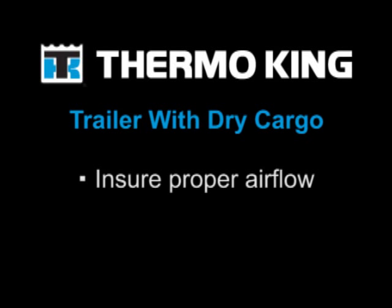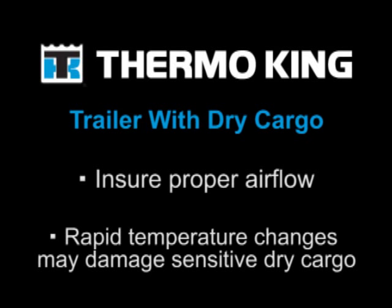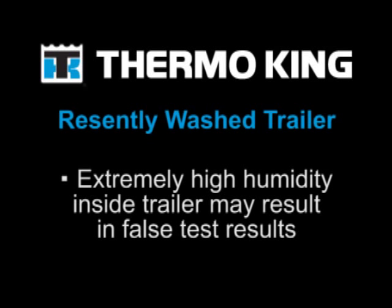If running a pre-trip test on a truck or trailer loaded with dry cargo, ensure that proper airflow can occur around the load. If the load restricts airflow, false test results may occur. Also, units have high refrigeration capacity, which results in rapid temperature change. Sensitive dry cargo may be damaged as a result. If running a pre-trip test on a truck or trailer that has just been washed down, the extremely high humidity inside the truck box may result in false test results.